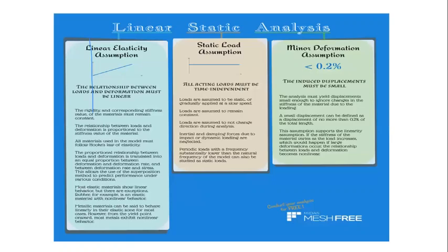In this slide, we looked at linear static analysis, what it contains, and the area of coverage. We looked at the linear elasticity assumption, which is that the relationship between loads and deformation must be linear. We looked at the static load assumption, which states that all acting loads must be time independent. And we finally understood that the minor deformation assumption states that the deformation will not be less than 0.2%.